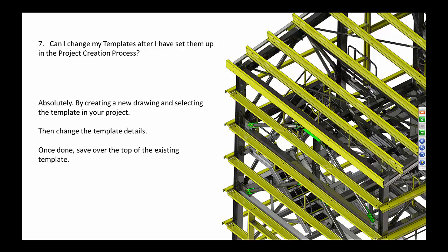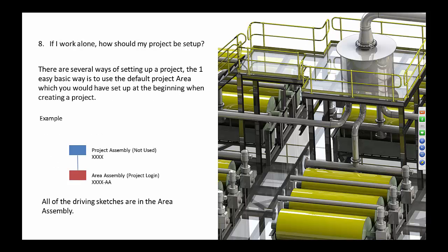Yes, you can, absolutely. If you create a new drawing and then select the template and make that the current template within it, then you can change the template itself, which is the drawing sheet template, and then you can save over the top of the existing one as long as you don't remove the crucial custom property fields associated to TSD. So if, for instance, a customer says, I want to put my logo on there, and it happens after you've created your project, you can certainly go in, add the logo, and then save it. Okay, now if you work alone, how should the project be set up?